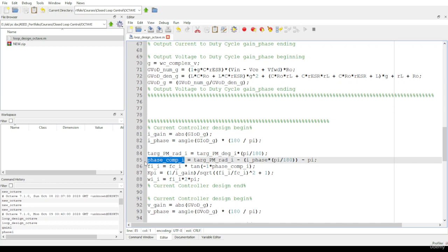They work out very well. So in the case where you need positive compensation, you should implement a lead lag compensator, not just a lead compensator. I suppose in some cases lead compensators have worked, but in my experience, they usually don't work very well for power supplies. Anyway, that's what you have there.